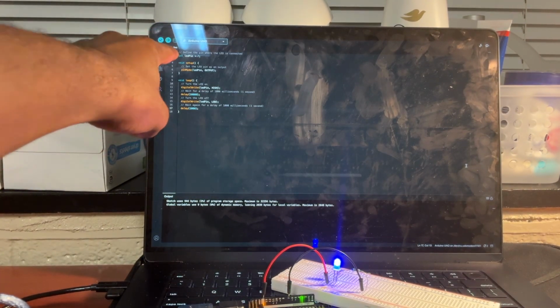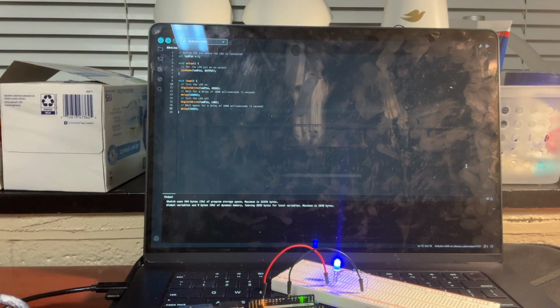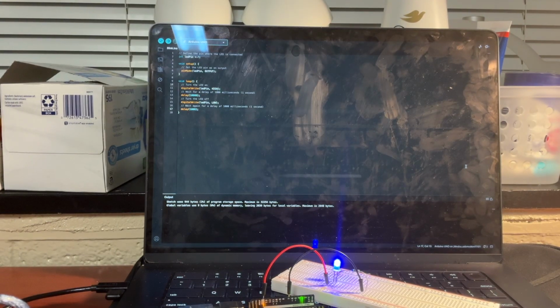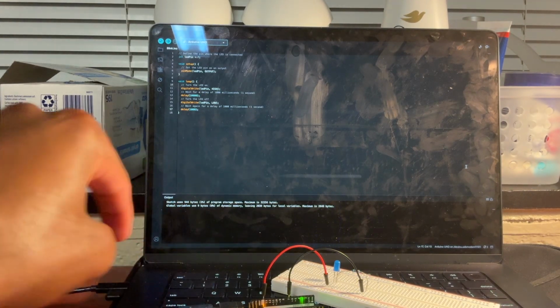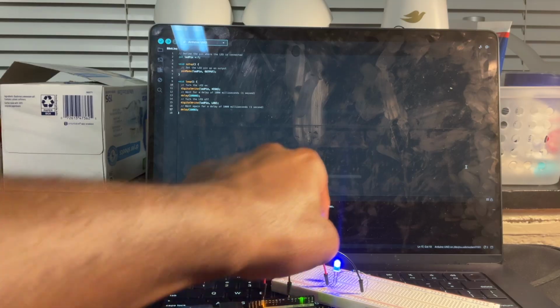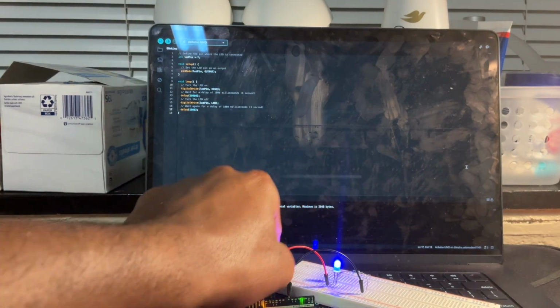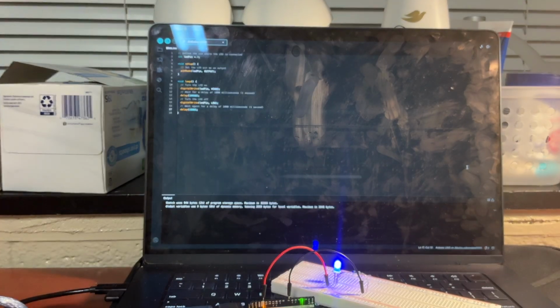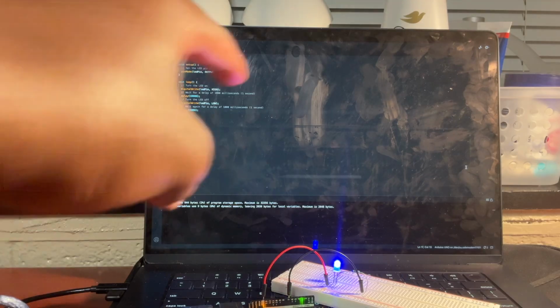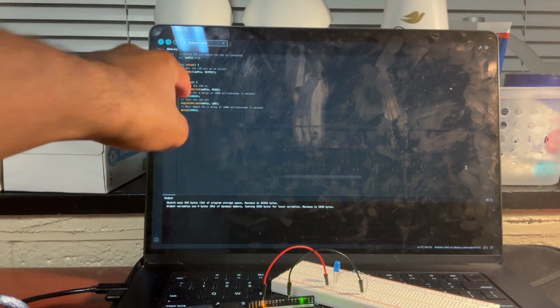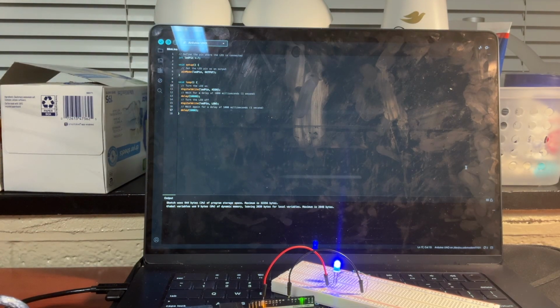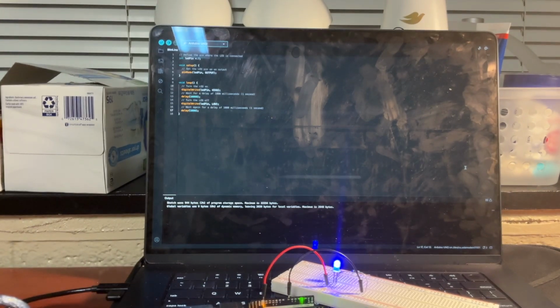First of all, this LED pin number 7 equals 7 allows for the transfer of the codes to the board through these two wires. This HIGH digitalWrite code turns the bulb on, and the first delay function of 1000 milliseconds leaves the bulb on for 1 second.